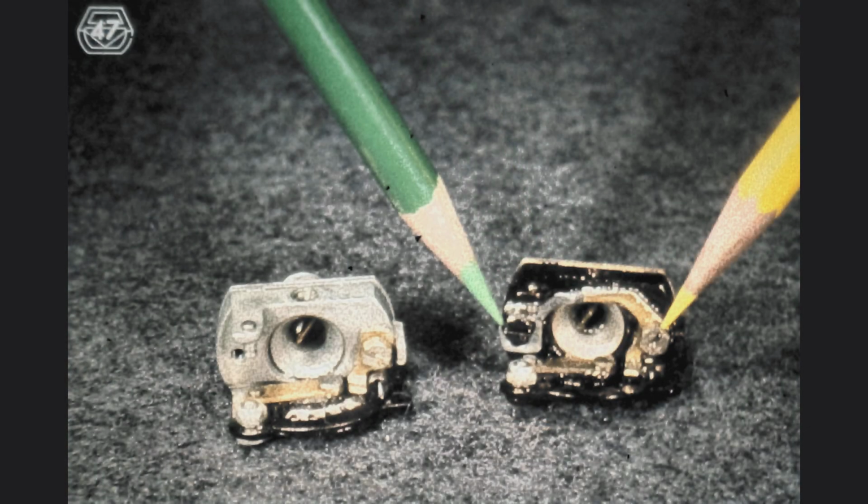Here we can compare the old-style tilt ring with the new-style tilt ring. The rotate detent shoes are substantially different. Notice on the new one, on the right-hand side, that the shoe is actually held by 2 screws, one indicated by the green pencil and one indicated by the yellow pencil. These 2 screws make it much easier to adjust the shoe.